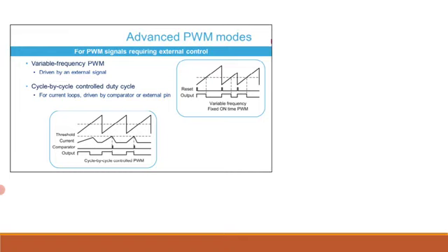The timer provides control for the on or off time using the compare register. The auto reload register guarantees that the PWM will not stop if the external reset is missing. This is an advantage, thus providing a safe control in boundary conditions. This technique is used for a variety of purposes such as transition mode PFC, power factor controller, for mains supplied applications and current controlled digital LED lighting, etc.